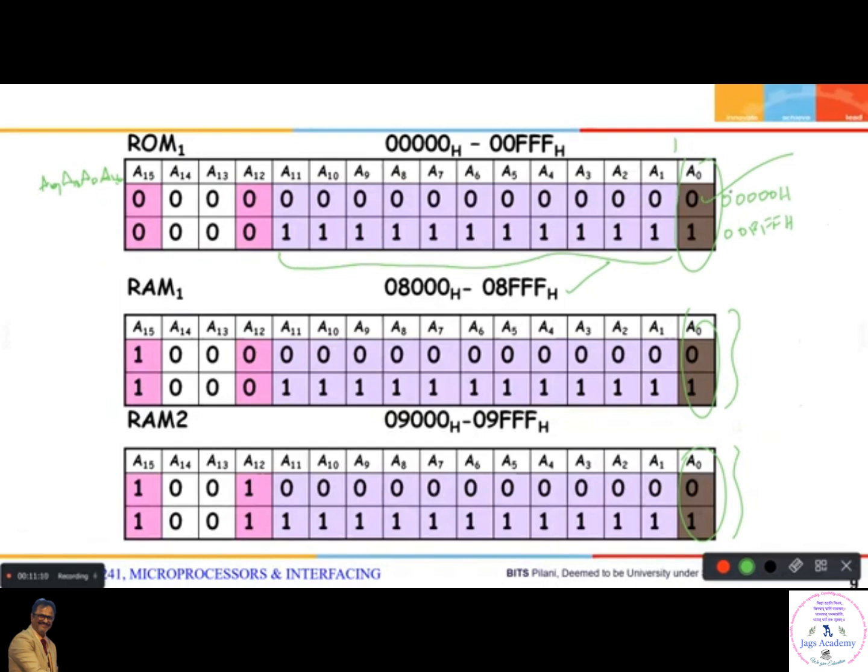You have many options here, right? But you can see A11 and A12. Can you check here which are the three lines? Just check. Already A11 will go to your address lines, right? What address lines are left, which you can give as input to the decoder logic?